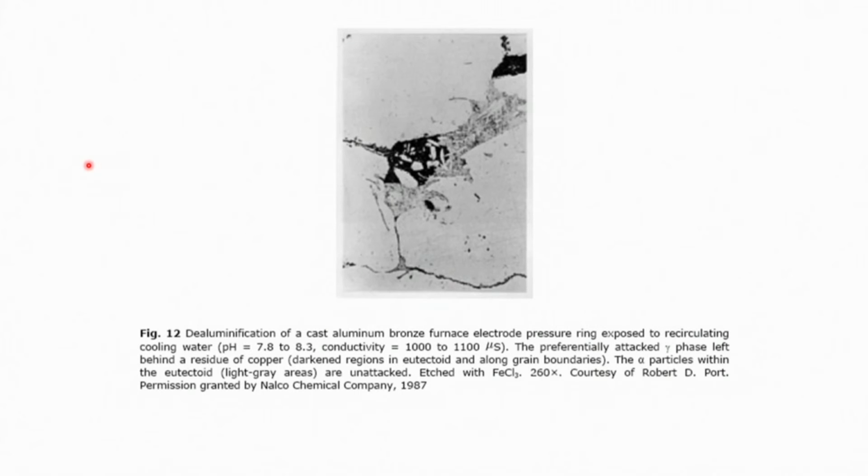If the grain boundary possesses any elements which are highly active or highly noble, particularly highly active, then the dissolution rate along the grain boundaries will be higher. On the other hand, if it is highly noble in nature, as in the case of 304 stainless steel after arc welding, we get precipitates of chromium carbide along grain boundaries. These are highly noble, cathodic compared to the surrounding boundary regions.